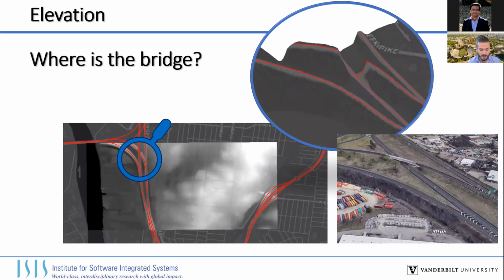The problem here is that usually these data banks work as a one-to-one function. You give a coordinate, and you get just one elevation for that specific coordinate. However, in a case like a bridge, you have 2 elevations, one on top of the bridge, one below the bridge. So this is another detail in data collection that you have to be aware of.